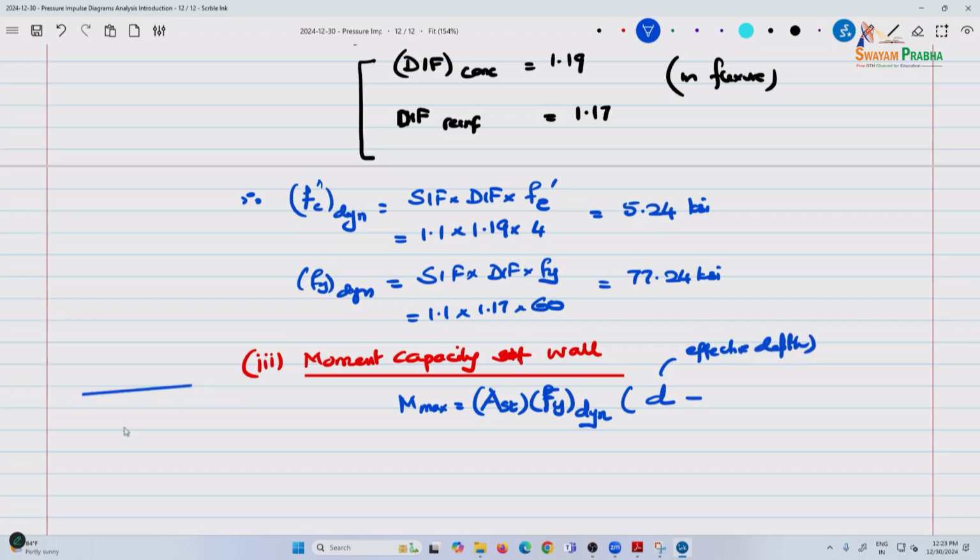So here we have the steel. Total depth is 8 inches. This is H, effective depth is D. This is the compression side, and this is the tension side. Remember that we assume that anything below this, the tension concrete, does not exist, right? So on the tension side, that is D, and this is the compression block, again I know it might be a challenge for mechanical.